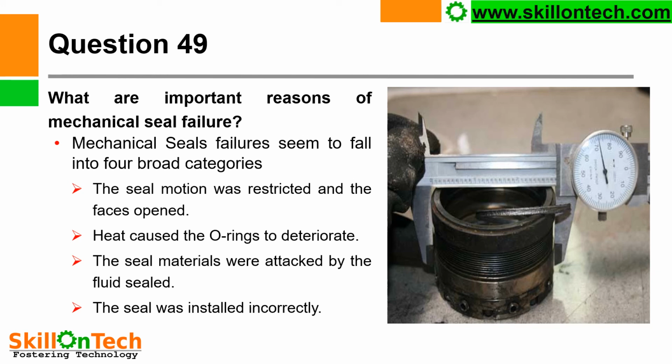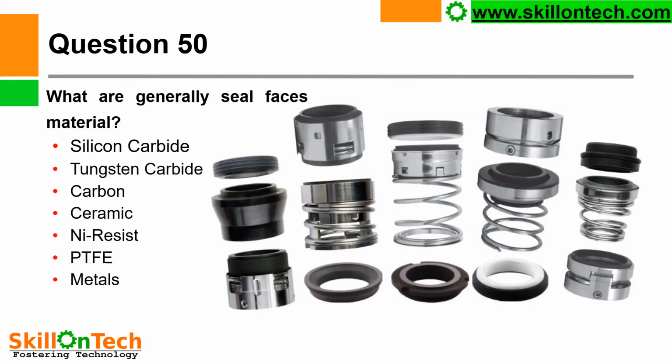The seal was installed incorrectly. If the seal is not installed properly with due care and a correct measurement, then seal will not function. Seal materials. Mechanical seal materials are shown: silicon carbide, tungsten carbide, carbon, ceramic, nickel resist steel, PTFE, polytetrafluoroethylene, or metals.